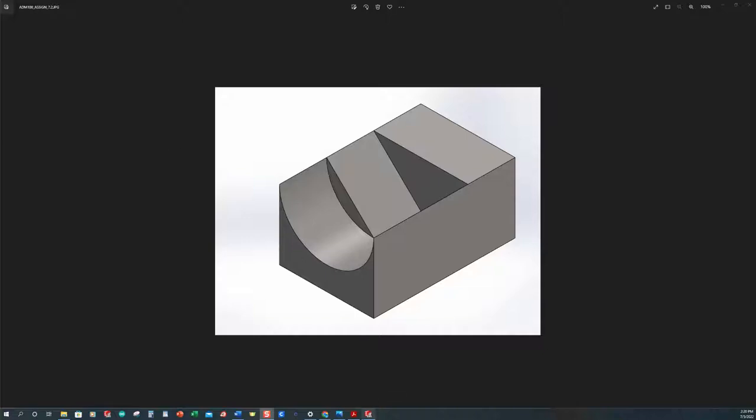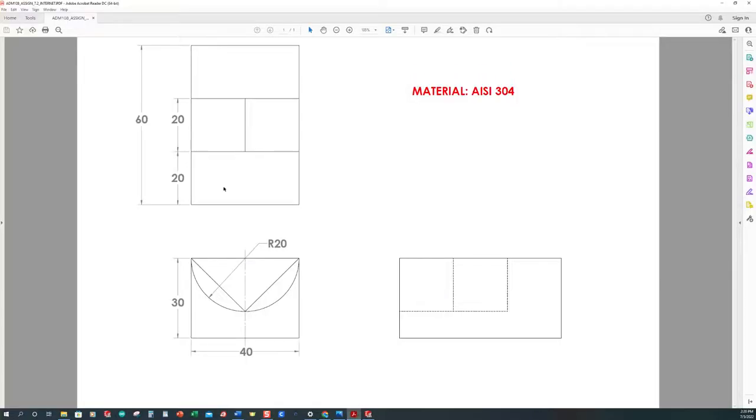before we walk. Dimension wise, we're going to be working with metric dimensions. So our default settings are typically set up for ANSI and inch, and I'm going to show you how to change midstream when we get ready to create a model. So when we've been modeling in the past, we've usually started on the top plane. This time I'm going to start on the front plane just to kind of change it up a little bit, and let's go ahead and get started.